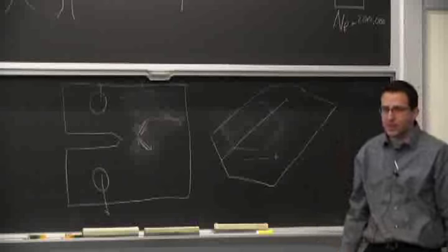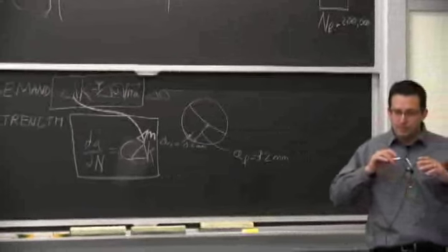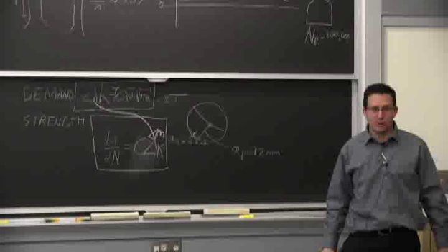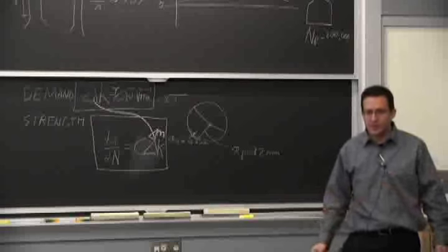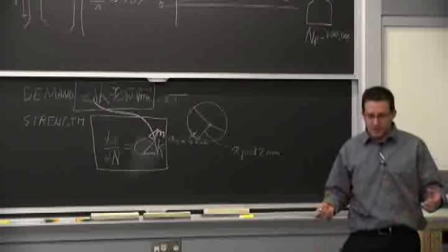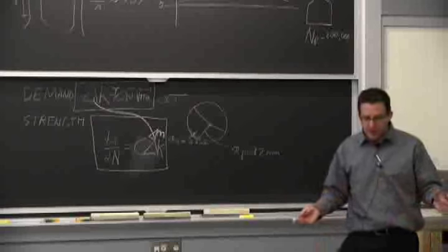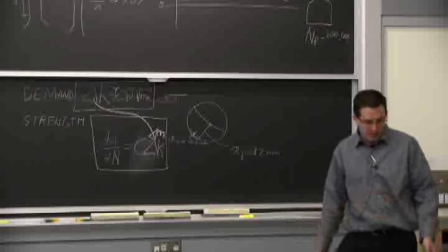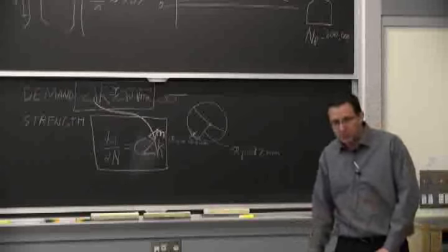And the reason why this is now less dependent on even grain size and a lot of other things is now we're deforming enough, we're really more into a tensile specimen type loading. We have a big plastic zone that involves more than the grain, and it's by blunting and resharpening the crack tip that we can form those striations.